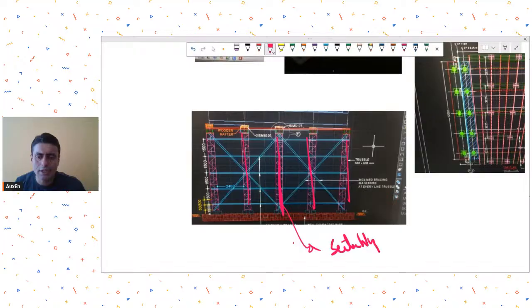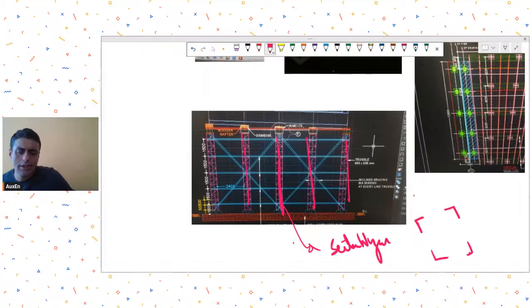So in the section wizard, you make your four angles. Don't model the lacings, just model the four-angle trestle. Import it into your STAAD using the UPT file, and then model these trestles as single line elements, with the property defined from the UPT file.